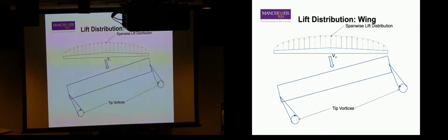But if I have a pressure differential here, so it's greater pressure here and lower pressure here, what happens? What do I get? I can get a vortex, but what's it called if there's a high pressure over there and low pressure over there and I'm standing outside? What do I feel? I get wind. I get flow. Flow moves. And that flow moves to eliminate that pressure differential. So I have either choice. The pressure differential eliminates itself, in which case there's no pressure differential between the upper and lower surface of the tip, or it remains. To remain, I have to have a step change, because they're right next to each other.